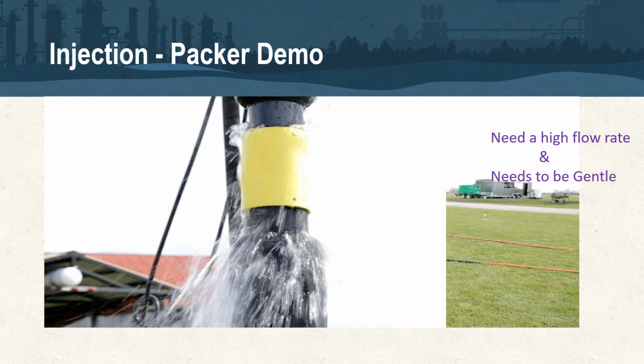We want to create a flooding. Not so much like a beach wave crashing, but think of a flooding event in the subsurface that fills up that feature, that fracture, and allows us to increase pressure for either a freshwater test or subsequent injection on it. So you can see there's the 18-inch interval. We increase the pressures there. And again, when we talk about pressures, there's system pressures, and then there's tip pressures or packer pressures. And Bill will explain that a little bit more in a second. But again, I think this is a nice example of what this actually looks like in the borehole from a display standpoint.